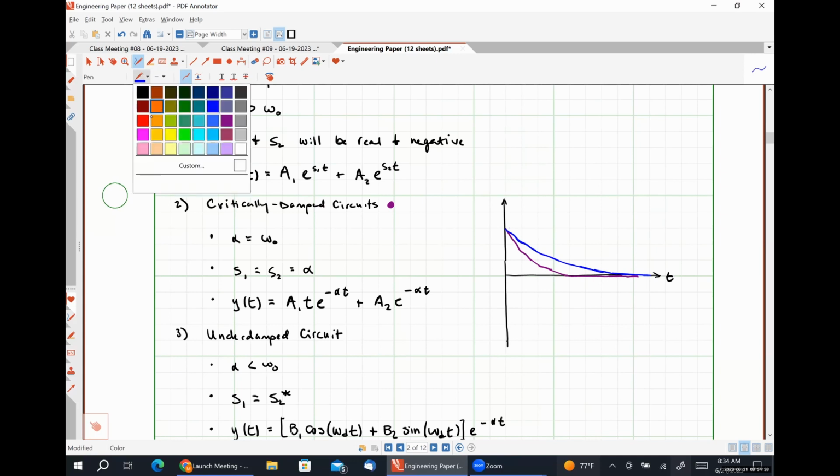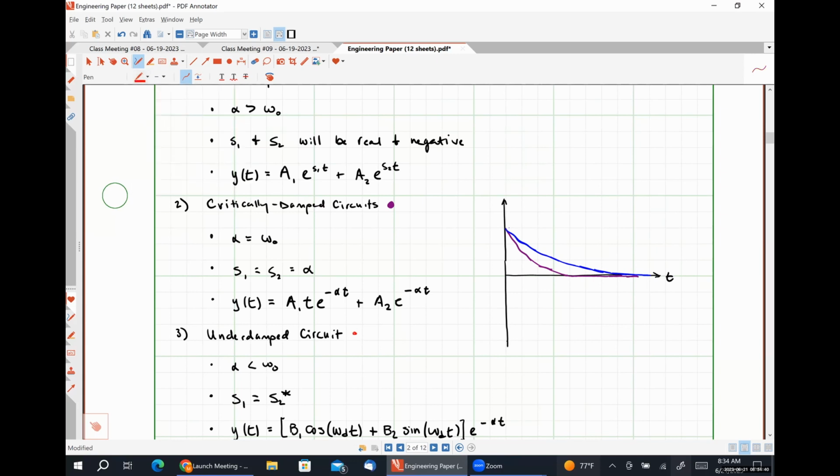Lastly, we are going to have a simple example of an underdamped response. And so for an underdamped response, we are actually going to hit our final value very quickly, but we are going to have overshoot or ringing, like so, or we finally settle to our final value over an increased period of time. Okay. So these are the three different responses that we might see.